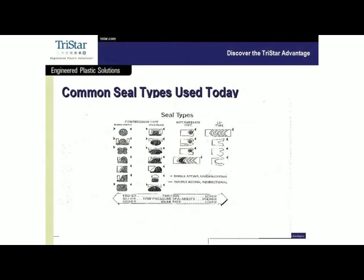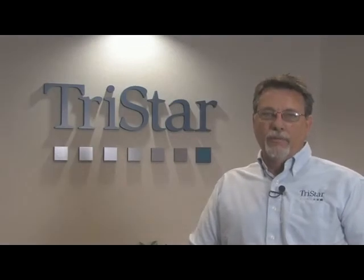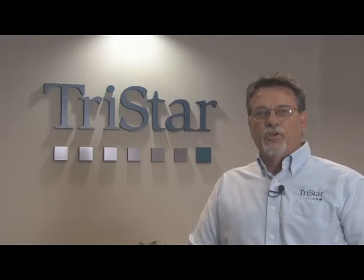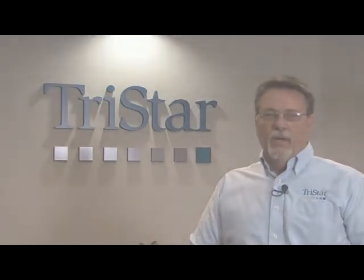Now, this chart that you're looking at is seal types as we know them today. Not very sophisticated. But you can see on the left side of the chart there's two columns, and these are considered to be classic compression type seals. These are seals that require a certain amount of either compression from a mechanical force, or they need a preload or an interference at their static condition in order to perform.